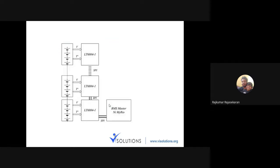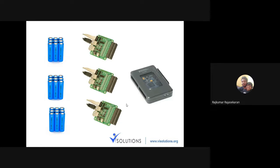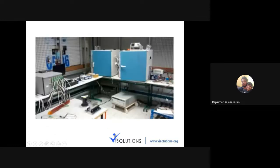Basically they used something like this. Different voltages from different cells were monitored by a single IC, and all this was connected by using the SPI bus. Using the SPI bus, they were able to send the data of the individual IC to the BMS master. So individual cells were being monitored by individual LTC ICs, and it was communicated to MIRI. Whatever data needs to be viewed and controlled was done by using LabVIEW. The LabVIEW is running internally inside the MIRI.